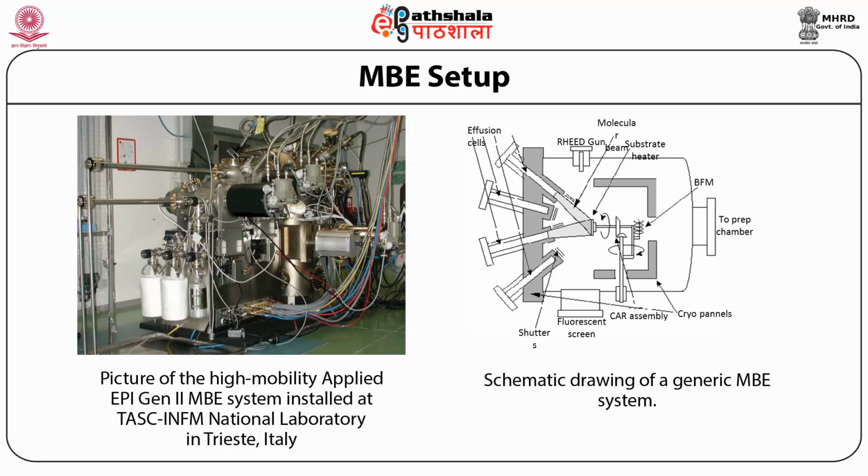It has slow growth rates which provide great control over the epitaxial layer thickness, excellent thickness uniformity, minimal foreign contamination as a result of UHV conditions, real-time in situ characterization during growth, and high quality multi-wafer growth for high volume production.